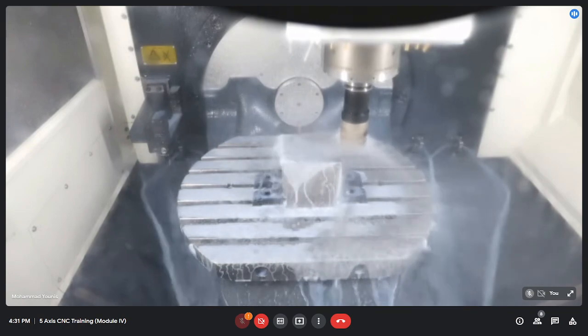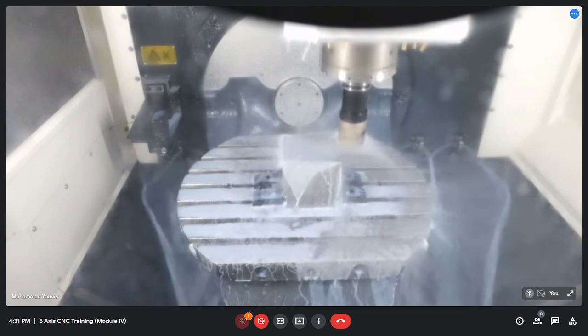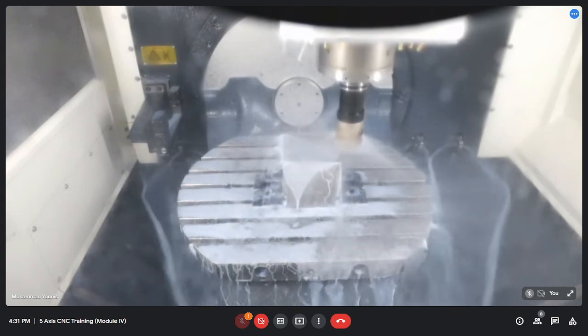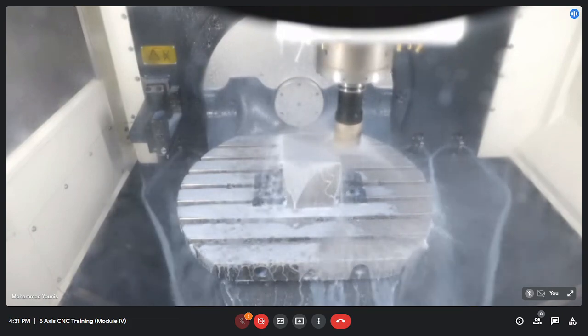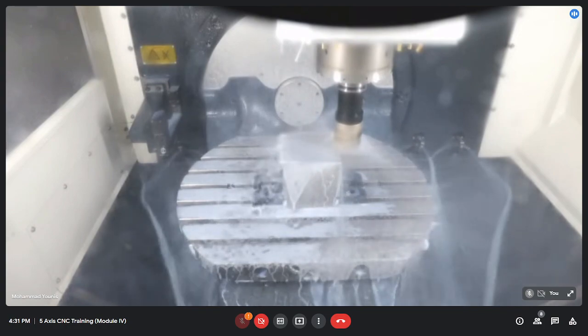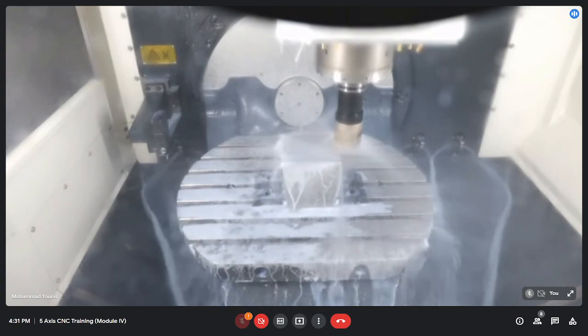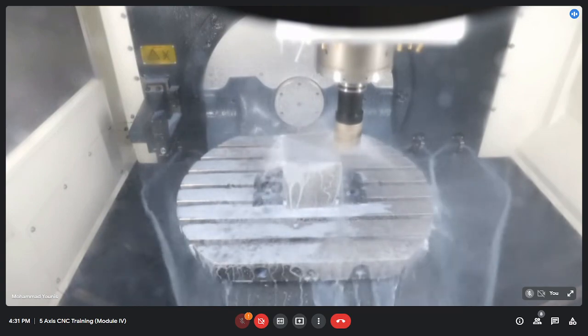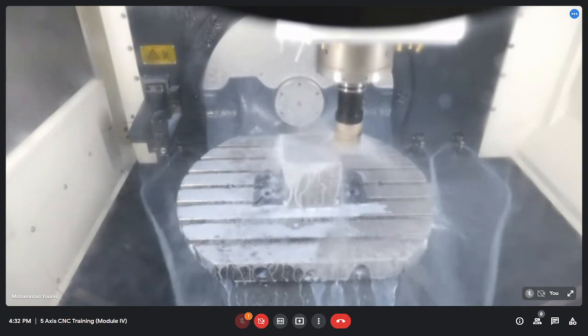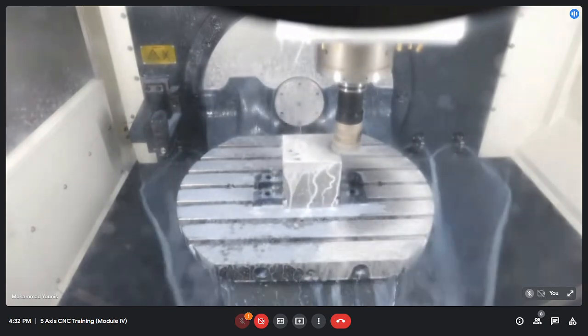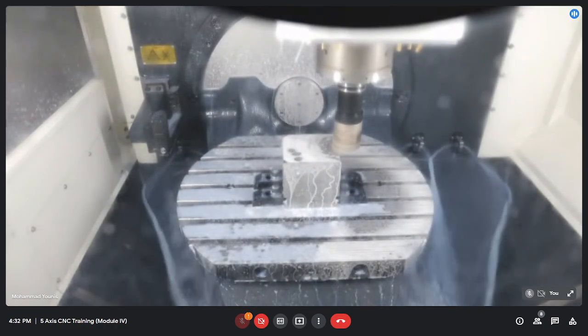Here, the depth of cut is 1 mm. Okay, I was supposed to change some parameters in the program, because this program is written so that the Z should be 0 there. That's why there is no cutting. That's good, because I have already removed 1 mm of material from the top surface. That's why there is no cutting, so this will be a free cycle.